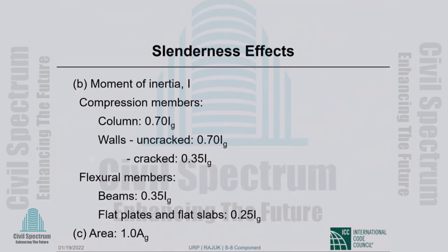The I, okay, most of the time you will use the I values given here. I would like to remind you that this is I think quite important. We are looking at section 10.10 of the code, slender column design, and the I values given here are for that specific purpose, design of slender columns.